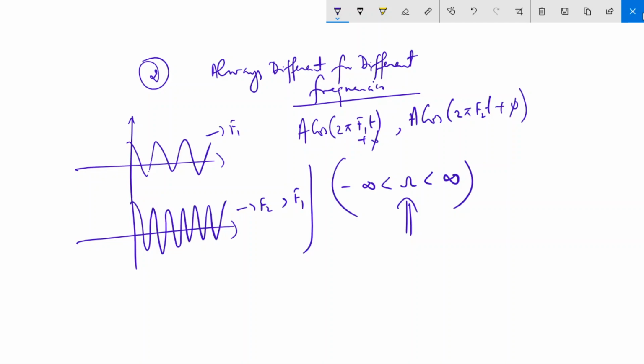And see, the concept of negative frequencies is very important. Why do we use negative frequencies? Because if you have a real signal, to express a real signal in terms of frequency, you must have a positive and a negative rotating phasor. Both phasors you must have. It means you have one phasor which is rotating with some speed in the anti-clockwise direction, and one in the clockwise direction.